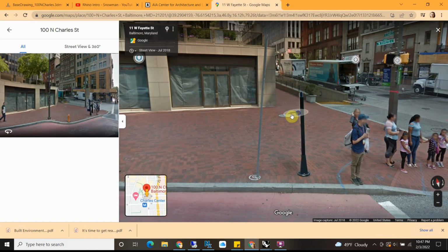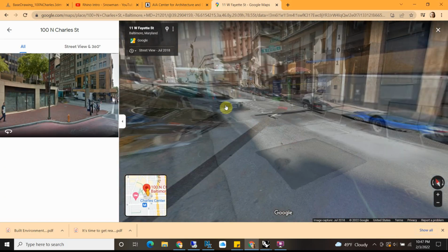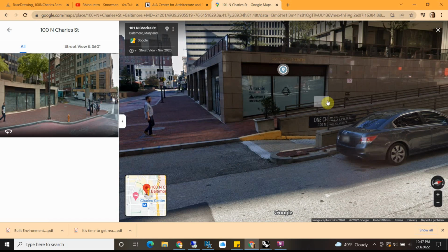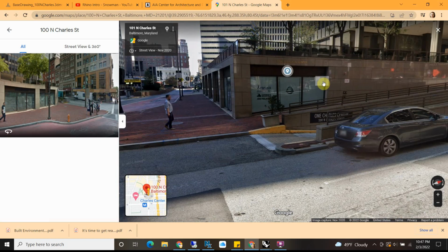So for our second cutout, what's a little bit complicated about our second cutout is that we have a ramp here. It looks like the ramp starts right about at the corner of our building, and then it continues up. I don't know exactly what the slope of our ramp is. I'm going to assume it's 1 to 12 because that is like a standard ramping height. That doesn't mean it is 1 to 12. It could be something different in real life, but that's what we're going to assume. So I want to draw the side elevation of this so that I can figure out where my cutout is really going to be here.